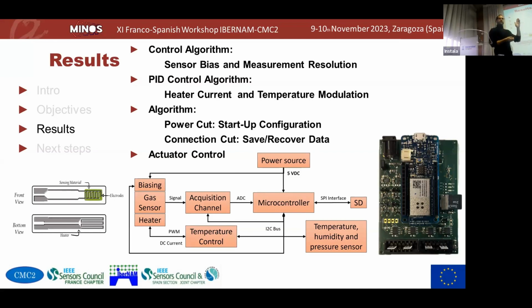And of course, we have the calibration curve related to the temperature and the current through that heater. And since we have this extremely fine control of that current, we can also make some temperature modulation and put in different waveforms if needed to get a better response from the sensor.